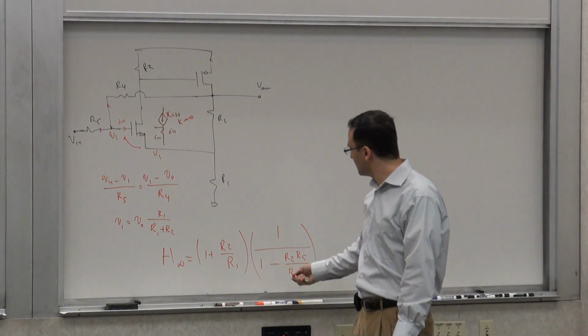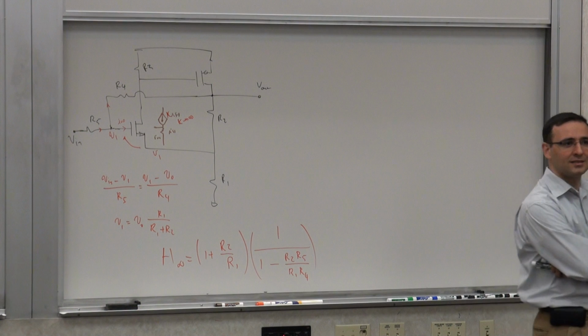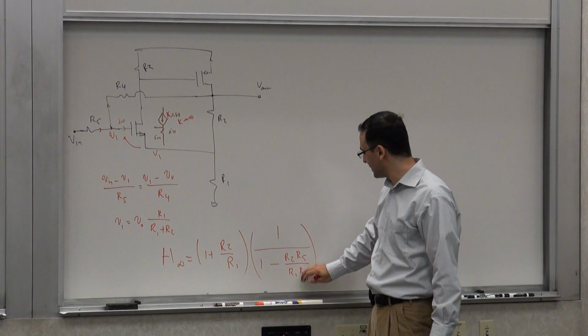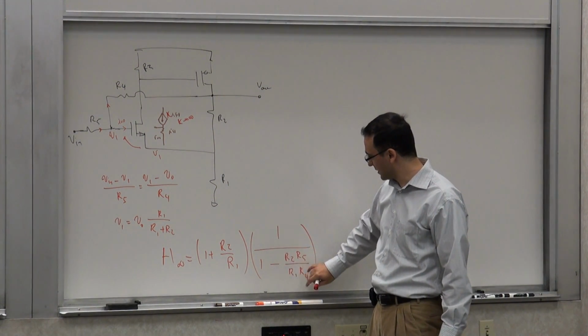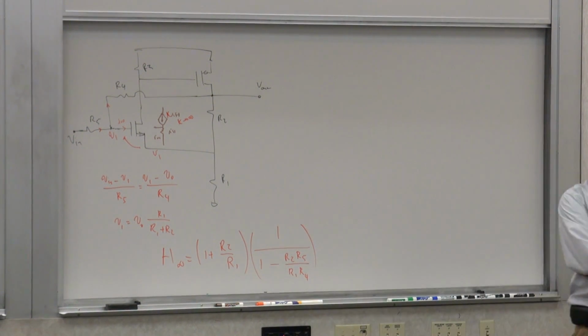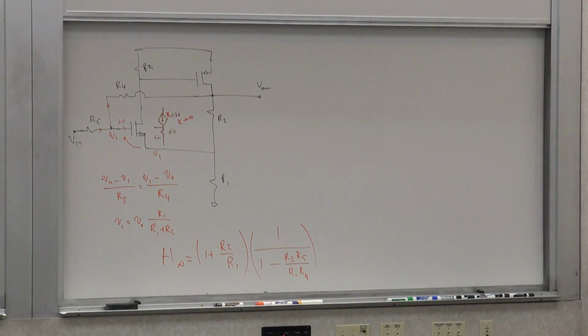Now R4 introduces this additional term that can change this. And you can see if you set R4 to 0 or to infinity, this becomes 1, because this becomes basically 0, this whole thing becomes 1. It goes back and reduces to the previous result. But now, this goes back to something you mentioned. You said, isn't R4 producing positive feedback? It is.